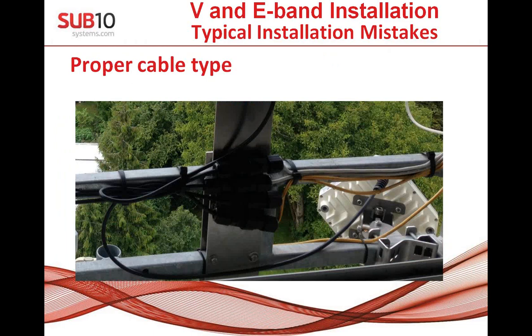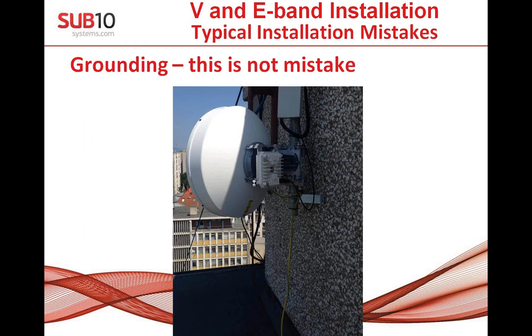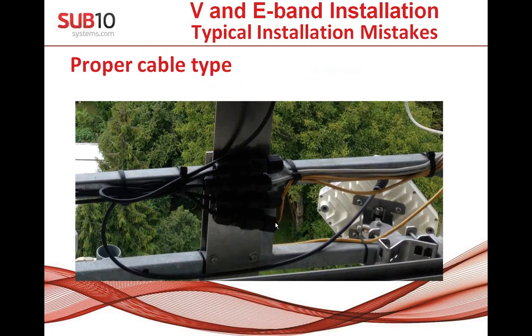Next, I mentioned proper cable. This is also from a real installation. You see the indoor cable going to the seal kit, and there are two issues. This PVC jacket is not designed to be affected by UV radiation for a long time, and mechanically it's also not so stable. And it happened at this customer that very soon, when the cable is going in, you can see damage on the PVC jacket, and very quickly it can also affect the wires. It was happening at this customer that the link was working, but the port was not able to go to gigabit Ethernet, just fast Ethernet.